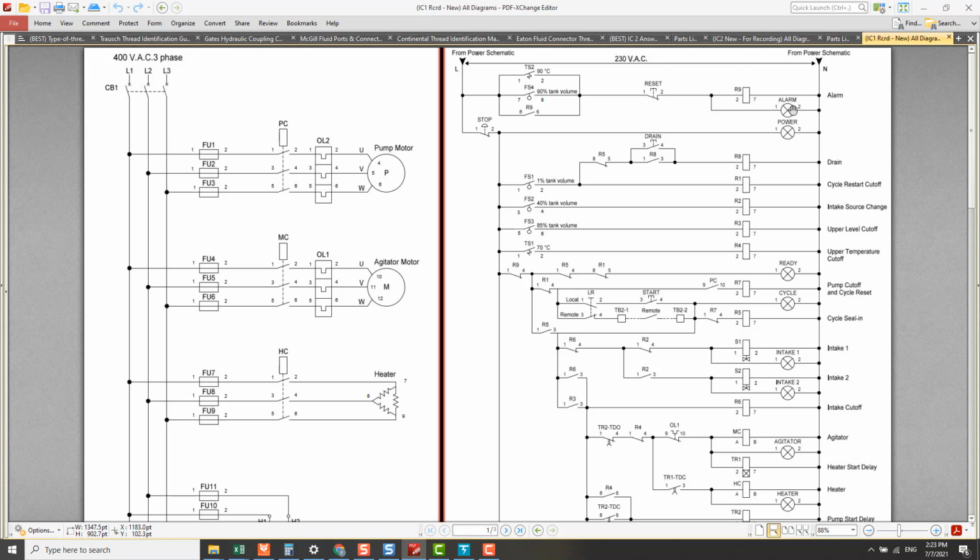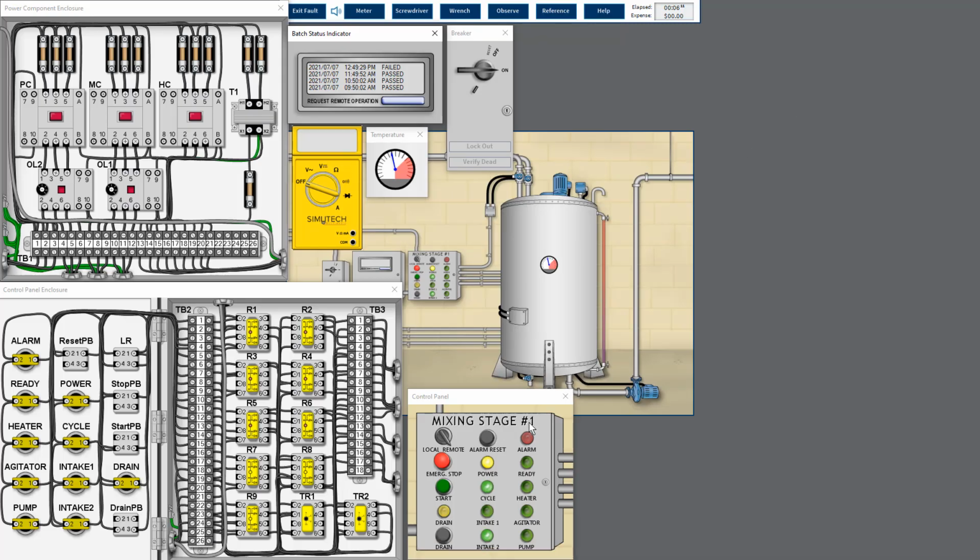However, the alarm lighting does not turn on. So most probably the alarm lighting has an internal open circuit, or the wiring has an open circuit or a loose connection.